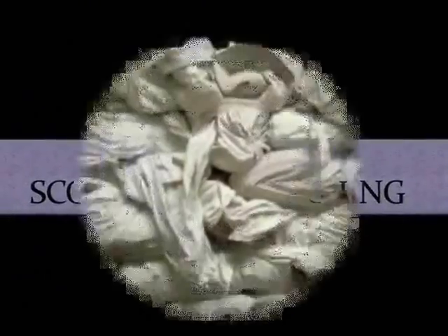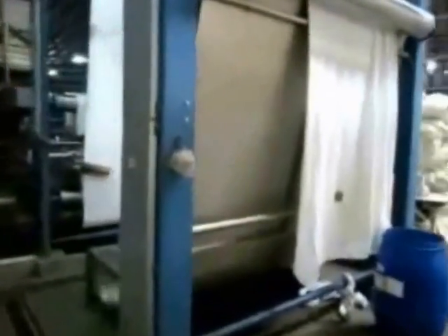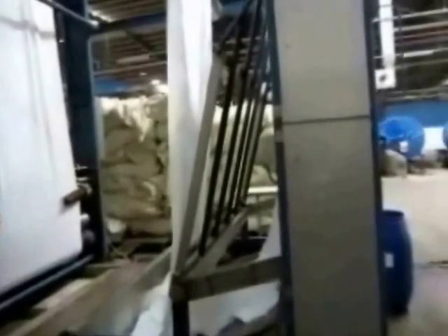Scouring and bleaching. Now we will see the scouring and bleaching section of this industry. In front of this machine, place a sewing machine to join the ends of two fabric for processing. This machine is used for high degree of whiteness, complete degrading of seed and removal of all impurities.